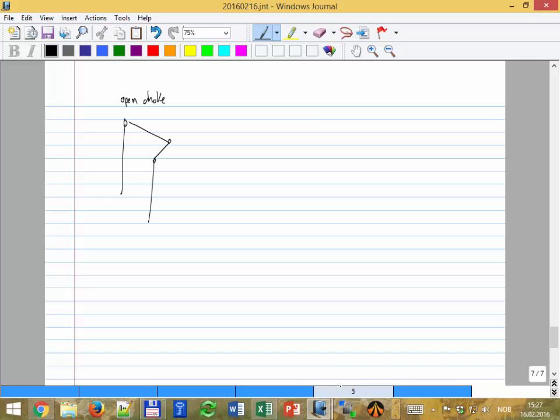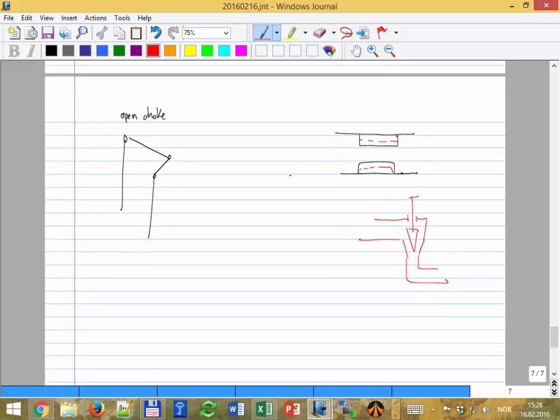So there are some chokes that are adjustable, where you can adjust and change the position, and there are other chokes that are fixed, called bean or positive chokes. It's a restriction you cannot adjust; to change the delta P, you have to change the whole cartridge. With depletion, you put in a smaller and smaller one. The adjustable one is just the figure that I showed before, where I can change the opening, the losses, by pulling this up and down. A bit. I will try to bring some pictures after.